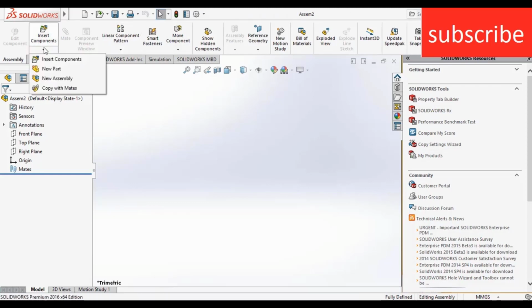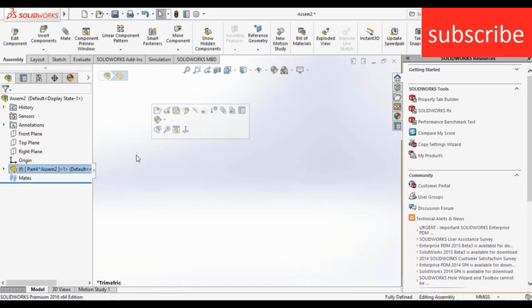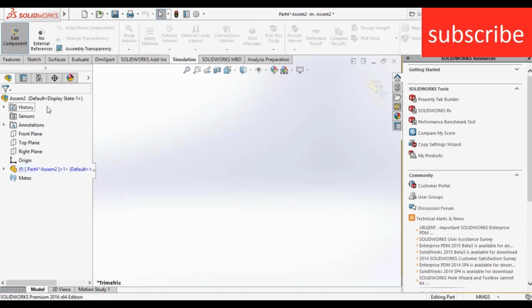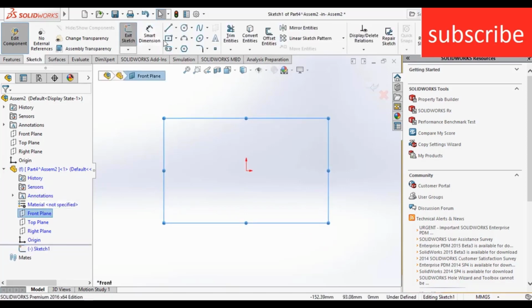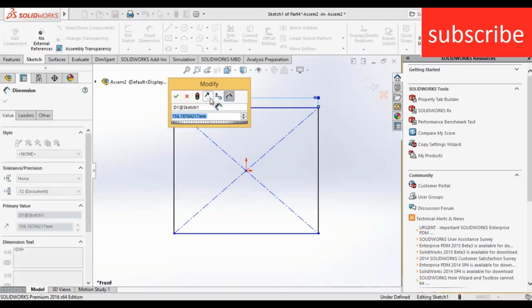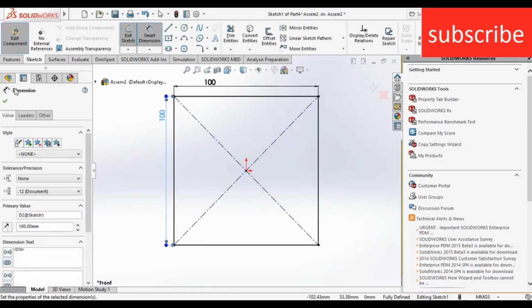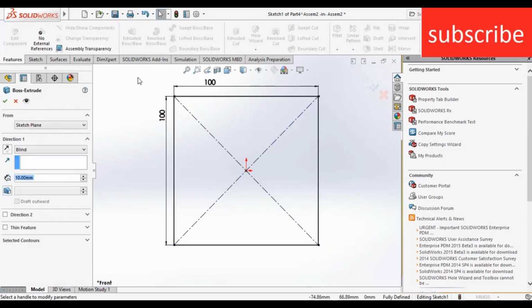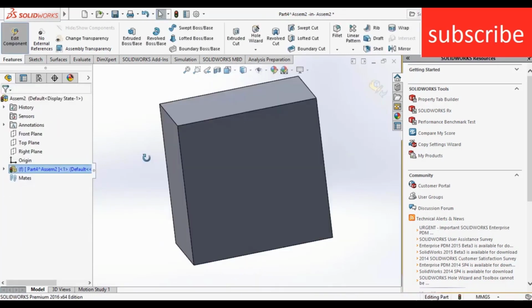So I am basically in assembly mode and click on new part. After that, select this new part and click on edit component. Expand this, select the front plane, click on sketch, press Ctrl+8. Now draw a sketch of 100 by 100 mm. Click OK and extrude it up to a length as per your requirement. Here I am taking it as 50 mm. Okay, here is our body.